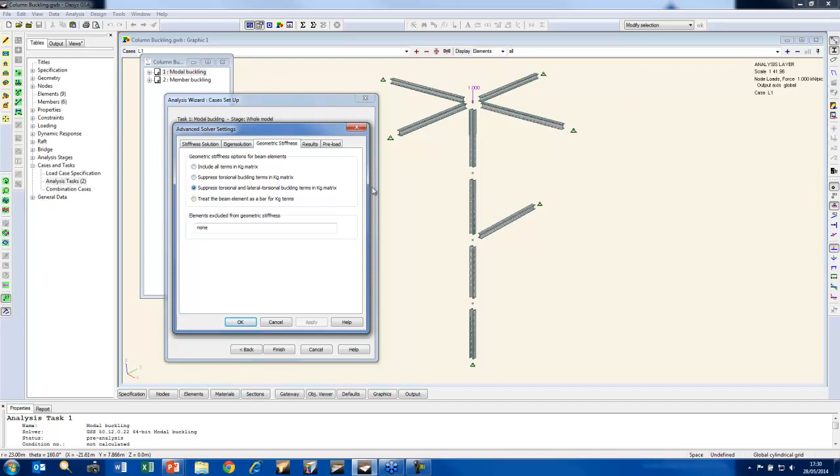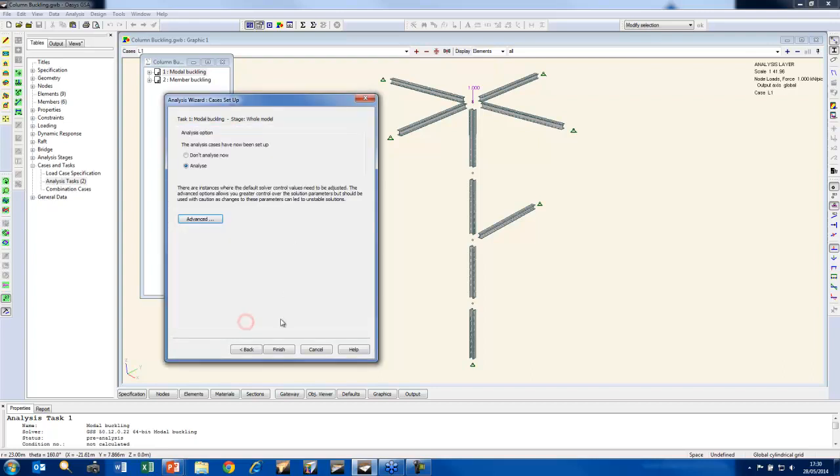In this case, we do results. I'm going to only keep the displacements. I'm not interested in keeping the moments and so on, because I know they're inappropriate and I haven't got preload in this case. So let's analyze that.